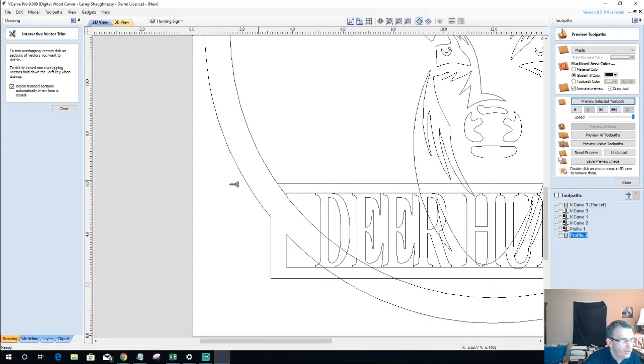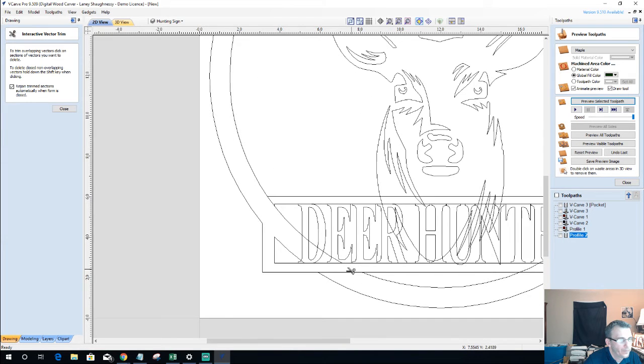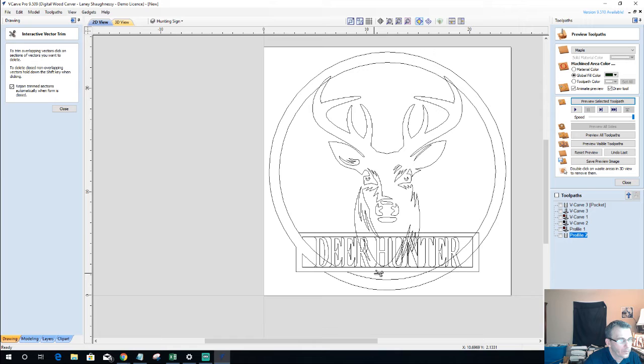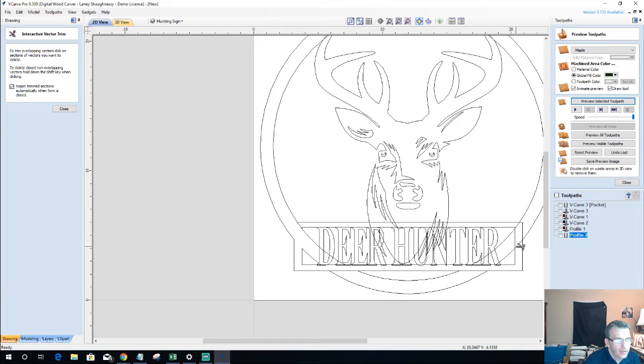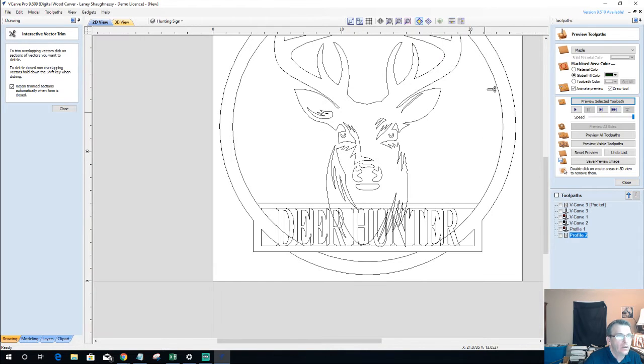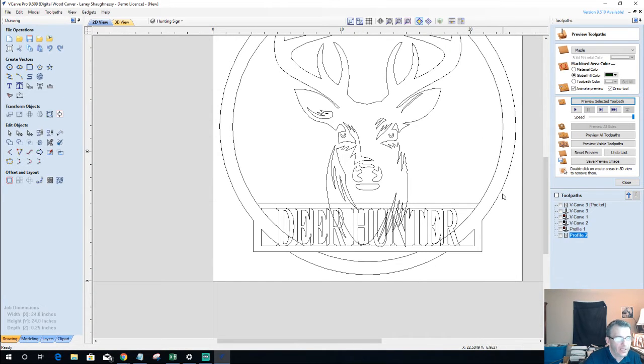And so I need to basically create this border. Okay. Maybe I want to keep that one. Yeah, I'll keep that and get rid of this and this and that. Okay, so I'm missing something here, right there, that line and that line. Okay, so now I've got my outer border. Let me close that trim tool before I click something accidentally. This outer boundary now has taken on the shape of this rectangle, which is fine.